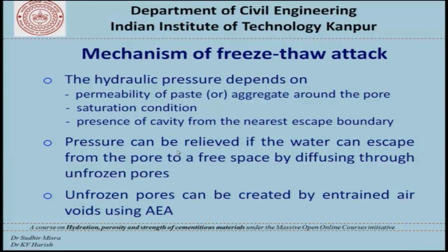Pressure can be relieved if the water can escape from the pore to a free space by diffusing through the unfrozen pores. Unfrozen pores can be created by entraining air voids using air entraining agents. If you do not use an air entraining agent, then you do not have unfrozen pores, and hence the entire concrete is subjected to freeze thaw cycles and finally expansion and finally cracking.